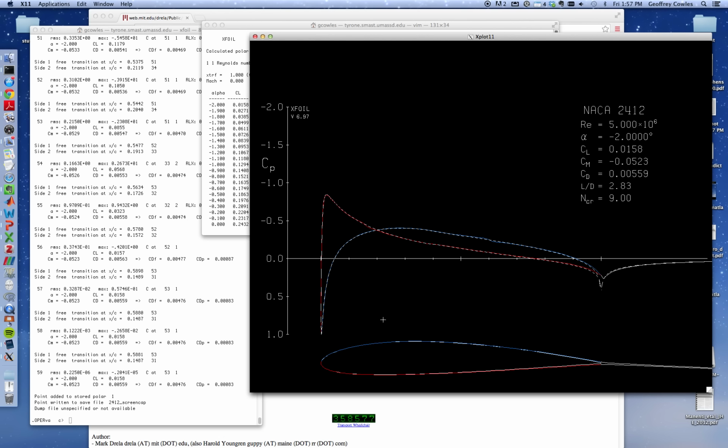They try to keep it laminar as far back as possible. So here, in this particular state, angle of attack, it is laminar on the top surface. Even at a Reynolds number of 5 million, it's laminar halfway back. You're getting to almost 2.5 million here because it's favorable for so long. It's a favorable pressure gradient all the way about here. So you're really not starting to mark the potential for transition until here.